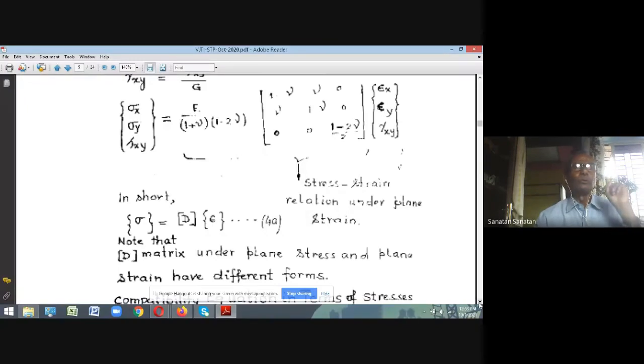So that's how we find that strains are related to the stresses in 2 dimensions. So it depends only on three stresses: sigma x, sigma y, and tau xy. I want to summarize that this stress strain relationship that we have got gives you one common point: the 4 stresses are not actually going to be independent. We have a case of just 2 dimensions.